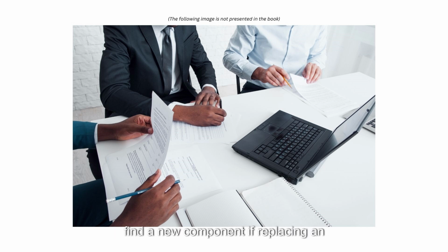Research to find a new component, if replacing an obsolete component. Library modifications to create or correct a symbol and/or footprint. PCB layout modifications, and any subsequent copper rerouting. Regeneration of the PCB documentation.